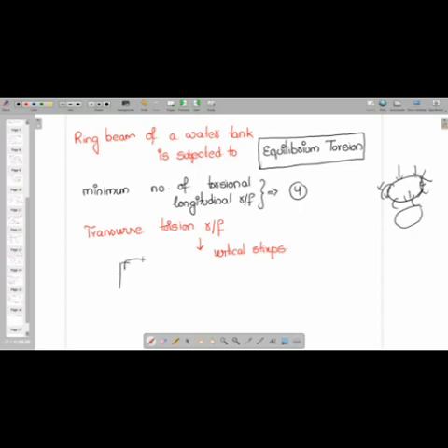Actually, if you see the stirrups, they will bend like this. In case of earthquakes, this is what they should do, which requires a skill level. And remember one more thing, students: inclined stirrups will become ineffective in case of earthquakes. Are you getting me?